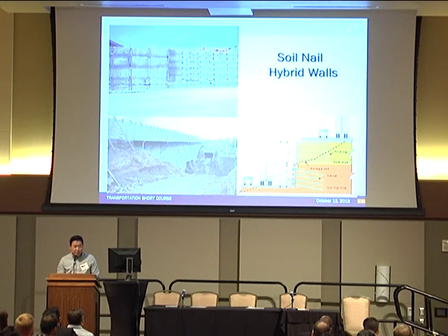The retaining wall drainage system is located at the end of the earth reinforcement as an under drain, and the soil nail drainage system is in front of the retaining wall, so it is hard to connect these two systems. In most cases, the capacity of the drainage system in the soil nail wall may not be good enough to collect all the water from the retaining wall.